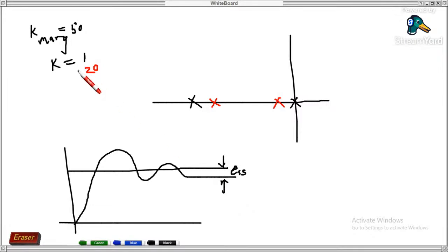I have increased the value of gain K, which means I will get a reduced steady state error. The error is less than before. But meanwhile it affects the overshoot. The overshoot increased.